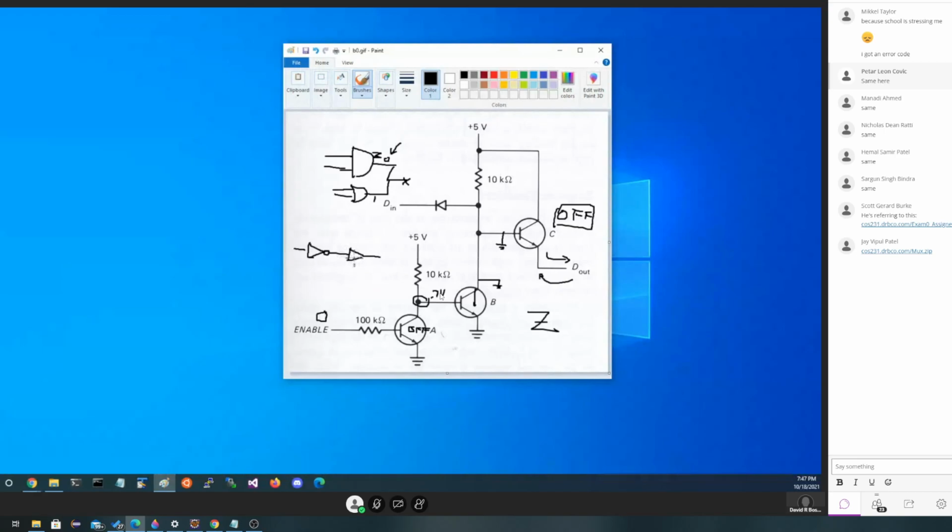It's a buffer, but we're going to give it a third pin. And the third pin is going to be the enable line. And that's going to be the thing that tells us we're tri-stating it. So what's on this side is 0s and 1s, and then what's on this side is 0s and 1s, as long as that's enabled, but a big Z there if this is disabled. So these tri-state buffer chips, or 3-state buffer chips, are going to be put in lots of places inside our CPU design, because we're going to have multiple things trying to write to the same inputs.